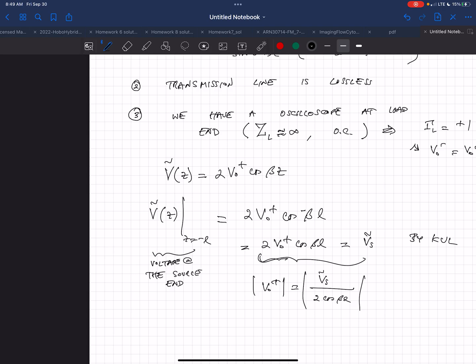Yeah. So this is only if Z sub S is 0? Then I can do a KVL at that point. Otherwise, only if V sub S is equal to 0 do I just have these two components for KVL. If Z sub S was not 0, there'd be a voltage across it, and I would have to include that in my KVL, which makes life a little complicated.